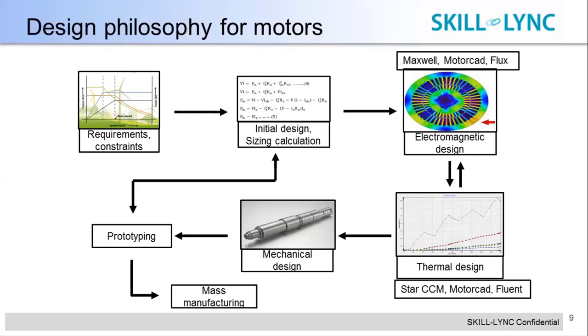It defines how much operating time the motor will be safe, and it has to be carried out in the very initial stages of motor design itself. Otherwise it will be a very difficult task to manage the thermal of the motors. Just after the electromagnetic design, we generally go to the thermal design, and generally there is a lot of to and fro between these two steps to come out with a stable or acceptable design.